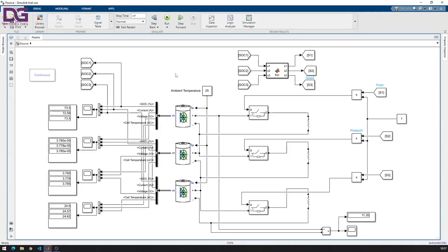So you are plugged in for more than 3 or 4 hours, and then there are some differences between your cell modules. So the battery management system will decide to go for either active or passive cell balancing techniques, and then balance these cells so that any permanent damage to the battery can be prevented. Thank you.